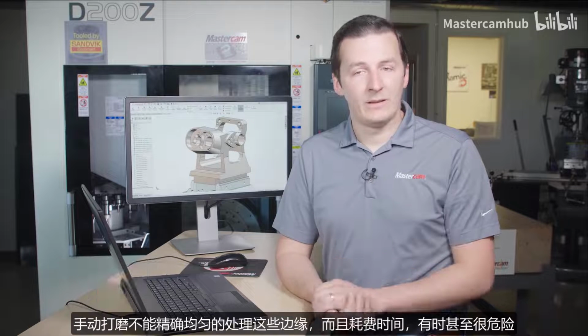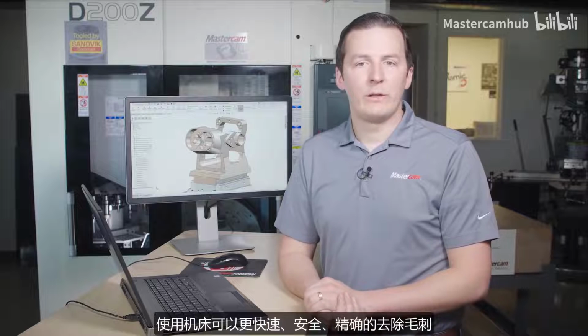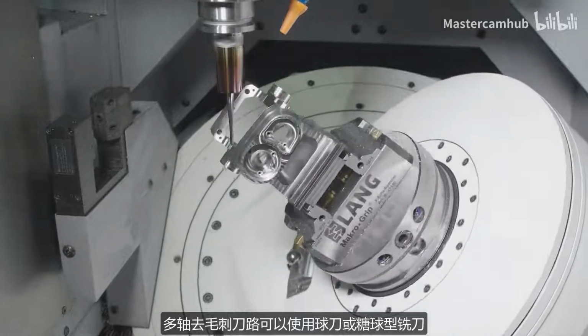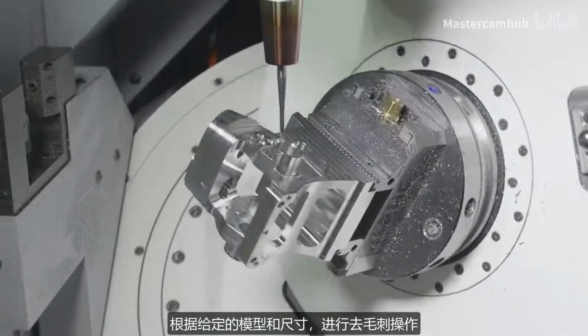Cutting a part like this, sharp corners and burrs are to be expected. Breaking these edges by hand can be inconsistent, time-consuming, and even dangerous at times. Deburring sharp edges on the machine is faster, safer, and completely repeatable. Multi-axis deburr uses a ball-nosed end mill or a lollipop mill to generate a machined edge break of a given size on sharp model edges.